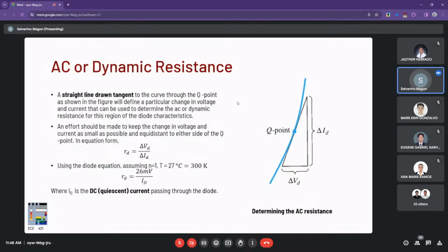And in doing so, we can approximate some resistance values through the Q point, no? Because you can see we have a slope, or the changes in current as a response to changes in the applied voltage, varies somewhat in a positive trend. So you have a positive resistance value here. And in a decent amount of the response characteristics, we have, again, a decent amount of linearity.